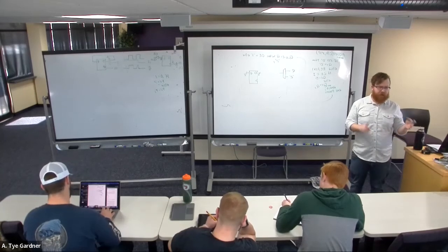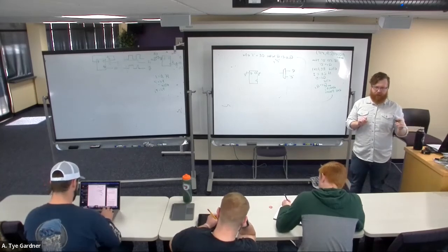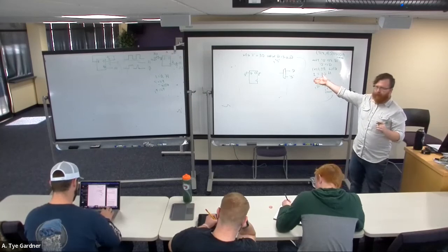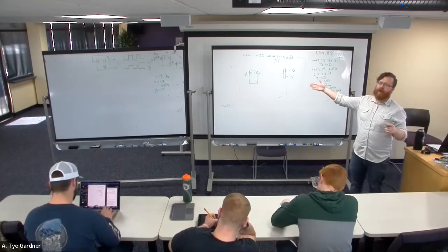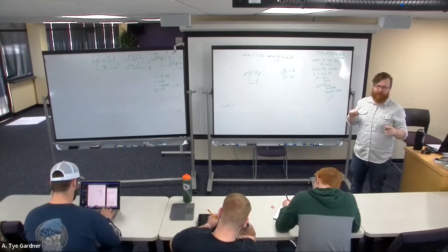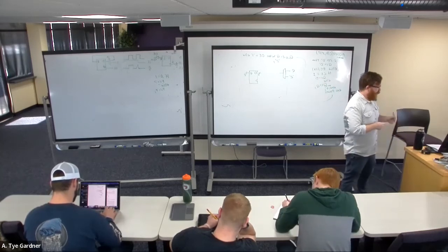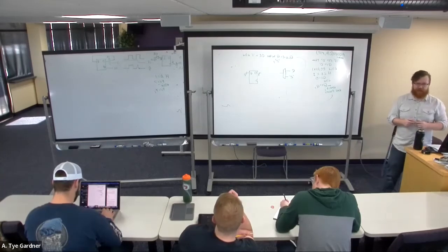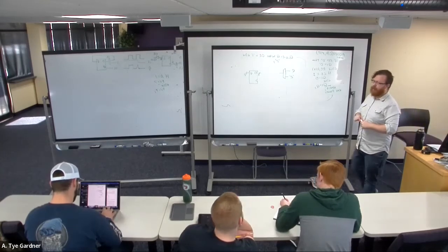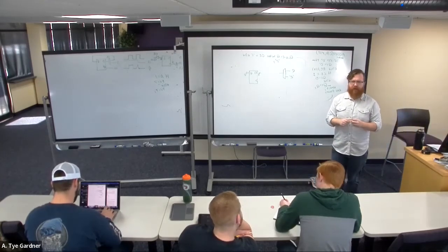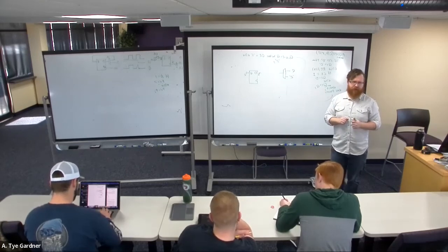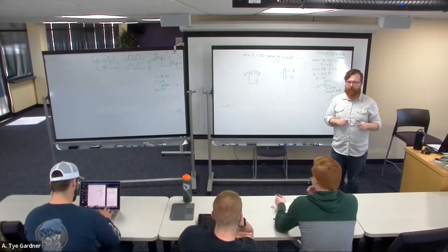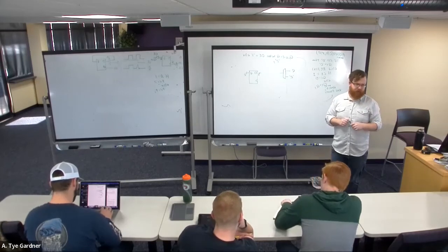Because one D flip-flop can't store more than 1 bit. So if I write the bus /8 saying that the bus size is 8 now, it implies that there must be 8 flip-flops. Once we start having those together, we call them a register. So that's going to be vocabulary that's going to pop up soon. In fact, we're going to build a very simple register in project 2 that's going to attach to your ALU so that it can remember the values that it started adding together.